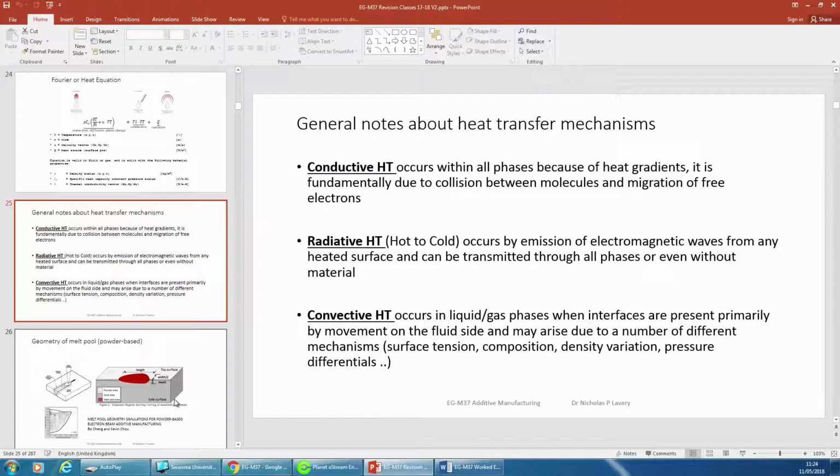It's there to make sure that it doesn't explode, since you're heating up a powder that could be pyrophoric. Other forms the convection takes are capillary and Marangoni convection, but sometimes with larger lasers you will also have thermal convection within the melt pool.